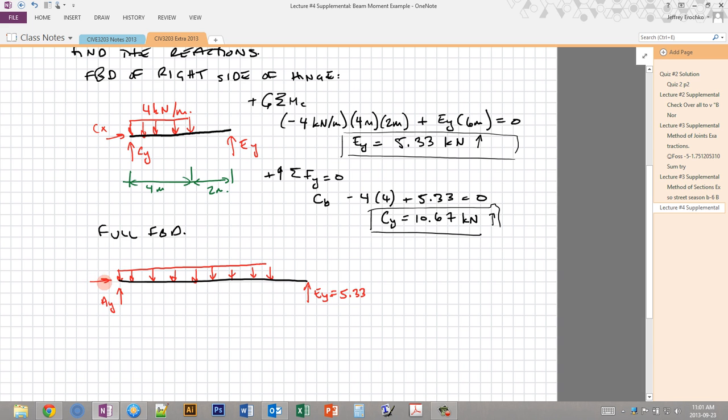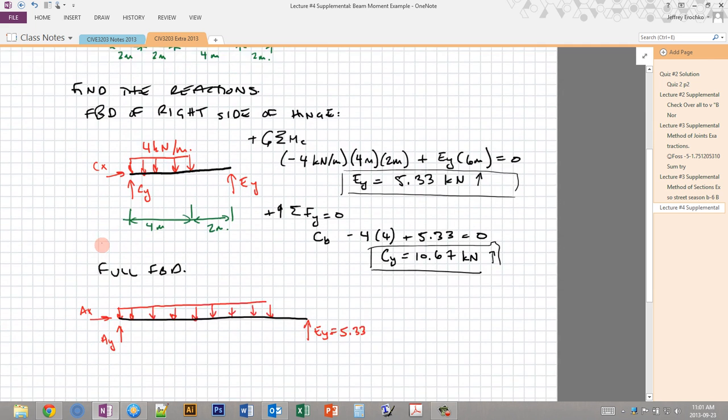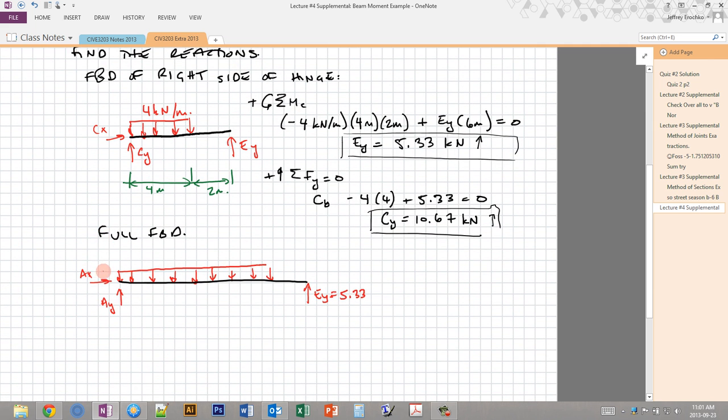So here's Ay, we have Ax. These are our reaction points at the fixed end. And since this is a fixed end, we also have a rotation. And that one, like this, is Ma. Now I've drawn this in the clockwise direction, which we can say is a positive rotation. But actually this would create negative bending, this MA. So you have to just watch your sign convention. But anyway, whatever you choose, just make sure to be consistent.